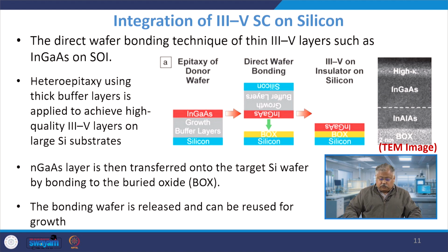If you look at the first one, I have this native silicon which is available to us, and then you put a buffer layer so that you don't allow any heavy materials or any other material to destroy your silicon. Over that buffer layer you grow indium gallium arsenide, and this is basically an epitaxial growth, right?